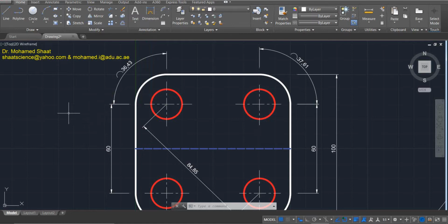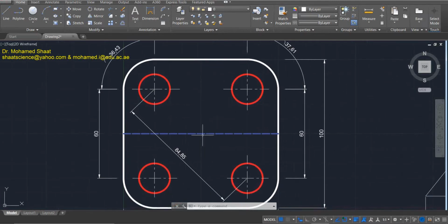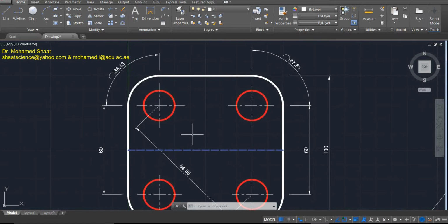Many people think that the diameter and the radius are both acceptable to represent the object, but it is according to the standard of engineering drawing. According to the standard, if there is a sector of a circle, it should be represented as a radius. Like you define the dimension of this sector as a radius.